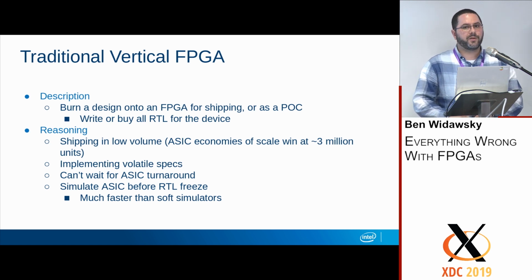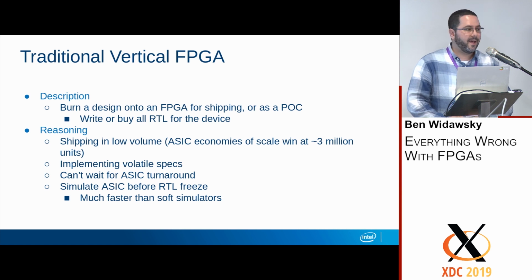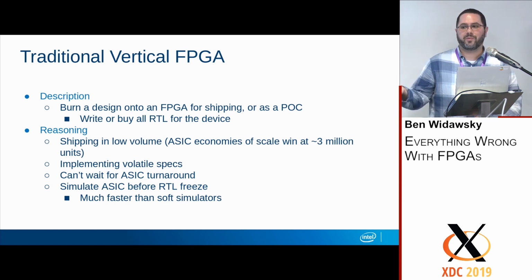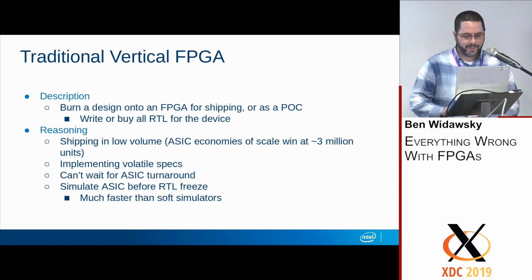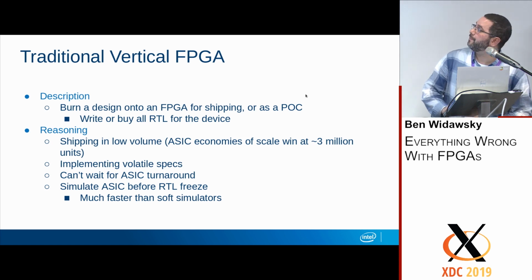So you can typically run in at least the tens of megahertz for complex designs, and if you want to validate your ASIC in any way, FPGA is actually a good option. And a lot of people in the room, I assume, who work on graphics, when they're using their emulation environments, really those are oftentimes backed by an FPGA, and that's why you do that.